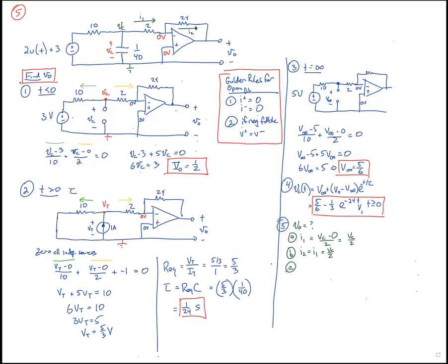The third step is to say, we want to find V naught. And it's great that we know I1 and I2, and it's great that we know the inputs are 0, but how do you find V naught? And the answer is we're going to say I2 flowing in this direction means we know that voltage. I'm going to call that voltage V24. We know what V24 is. It's got to be equal to, by Ohm's law, just I2 times 24. We've defined it the right way, entering more positive and exiting more negative.